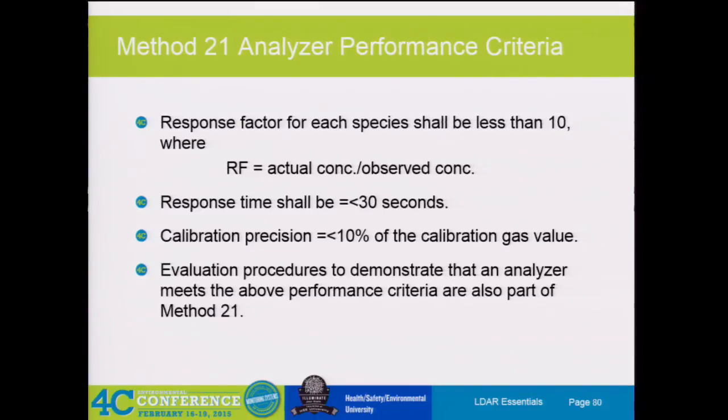So we started really just troubleshooting ideas, and when he would put it on his back, and the way that it would sit, it would actually bend into the housing, and he had about the end of an eraser pencil hole in his probe tubing. But when it was laying flat without any pressure on it, it was closed and he'd get the right reading from the calibration gases. But when he got in the field, just by the way that it changed, this hole would open up, and so he was just basically sucking ambient air in. And so that's another thing to look for. And I'm sorry, that was a little off topic.